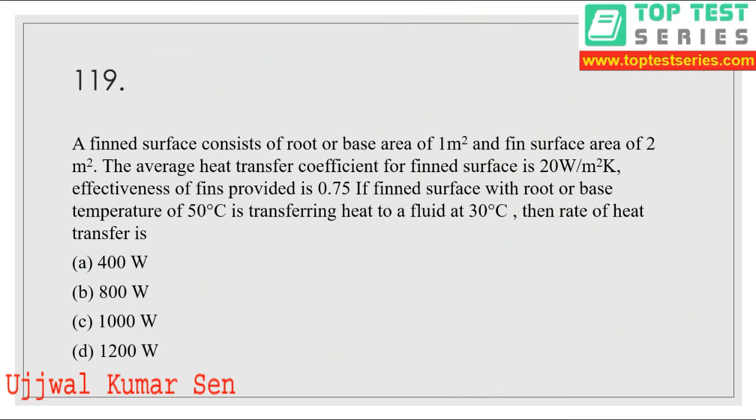Question number 119. Again, a very good question. A fin surface consists of root or base area of 1 meter square and fin surface area of 2 meter square. The average heat transfer coefficient for the fin surface is 20 watt per meter square Kelvin. Effectiveness of fins provided is 0.75. If the fin surface with root or base temperature of 50 degrees centigrade is transferring heat to a fluid at 30 degrees centigrade, then we have to find out the rate of heat transfer, that is, Q.